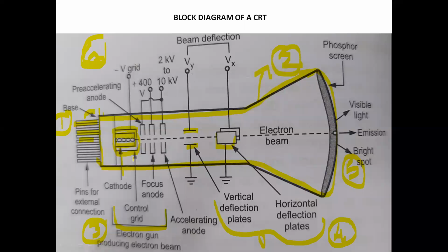We take a heater element and heat the cathode with that heater element. So since this is an evacuated glass envelope and here is a cathode and that cathode is heated, what happens? Obviously, a number of electrons will be generated around the cathode. They are not having any specific direction. They are lightweight ones. They have no inertia. So what happens? They move randomly around the cathode.